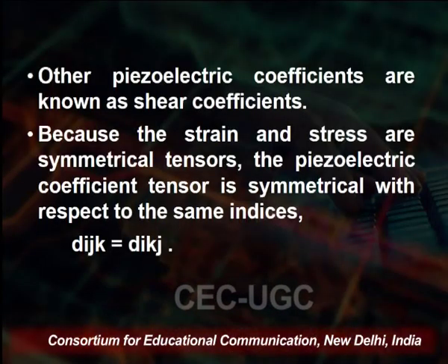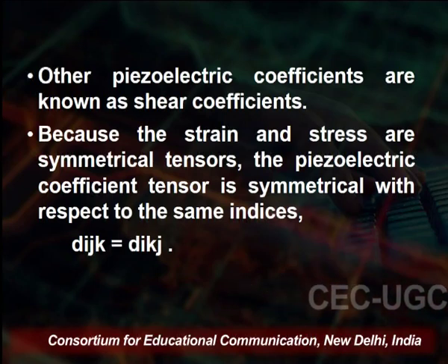If the coefficient is measured in the direction of the applied field, then it is a longitudinal coefficient. Otherwise, if it is perpendicular to the field, then it is a transverse coefficient. Other piezoelectric coefficients are known as the shear coefficients, which may be applied in any direction.